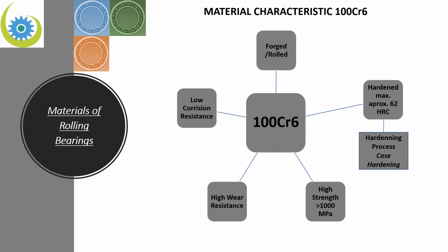Disadvantages here, and this is important, as also indicated here, is the low corrosion resistance. Because of this issue, please take into account that lubrication concerning rolling bearings is not only important if we use them in operation, it is also important for the handling or storage of them. For example, if we store our rolling bearings in our warehouse, we must assure that they are lubricated.